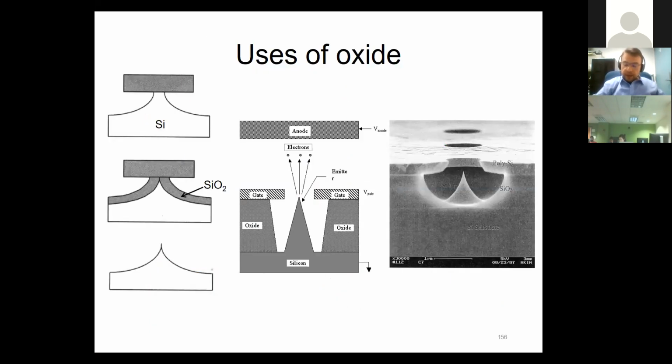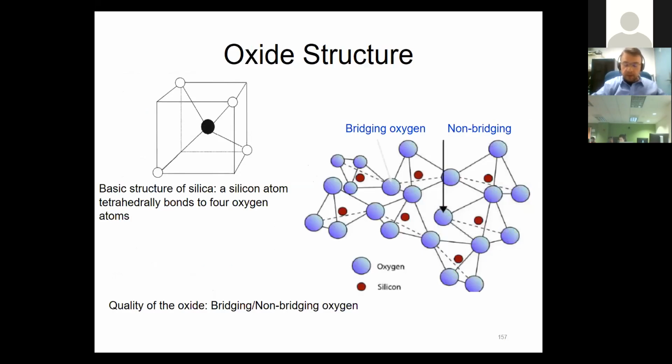All right, the thing that I want to emphasize is, since silicon dioxide is a native oxide of silicon, it will actually consume the silicon while we're growing it. So you see, if you have this kind of formation and you grow the silicon dioxide on the top, while you're growing the silicon dioxide, you're consuming the silicon underneath, so it doesn't stay at the same level. That's very critical, and we should never forget that we're consuming the silicon in the first place.